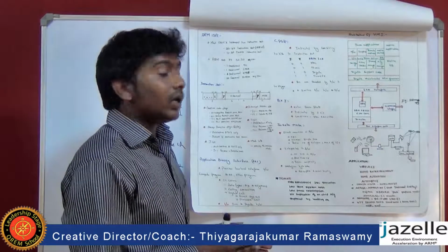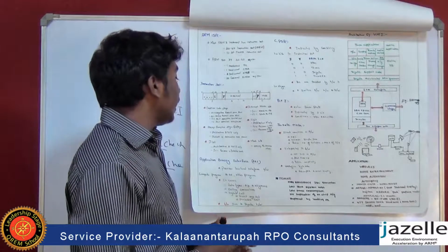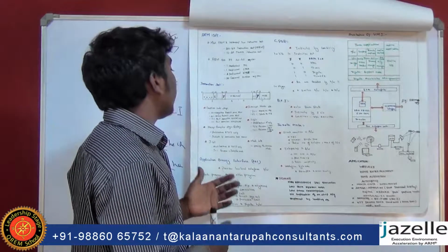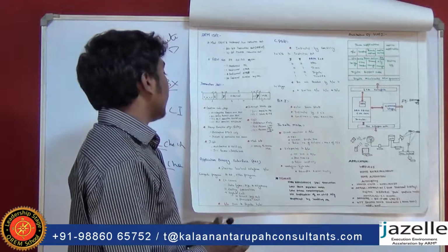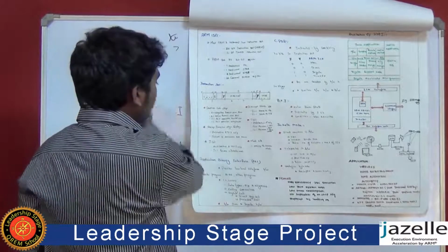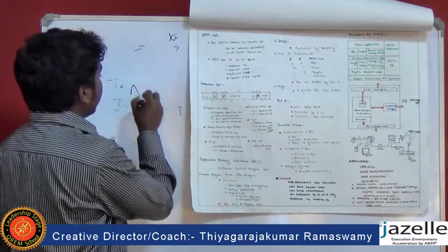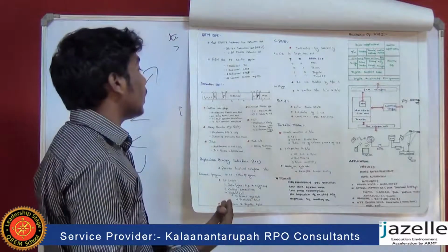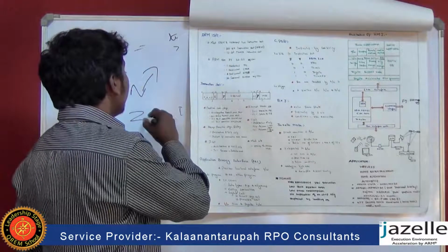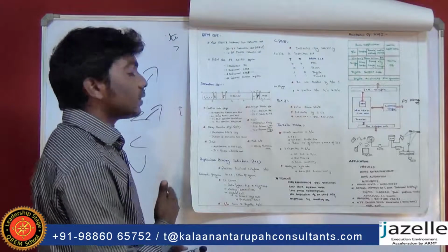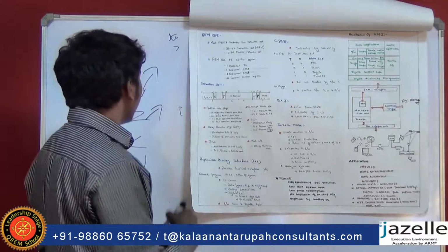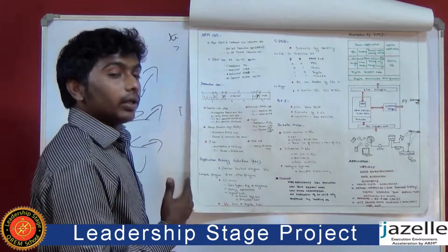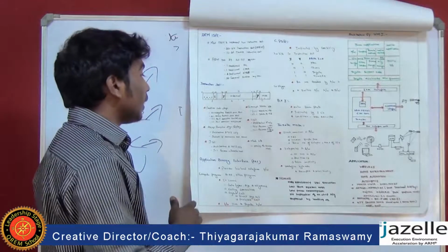And the next bit is the Q flag, that is the sticky overflow flag. It is also available only in architecture 5TEJ. It indicates whether saturation has occurred or not. And the next 4 bits are the condition code flags, that is N, Z, C, V. N is used for negative results that come out from the ALU. Z is used for zero result output from the ALU. C is used for carry out of the operation that is carried out on the ALU.